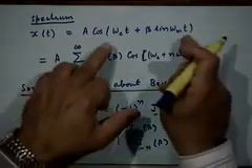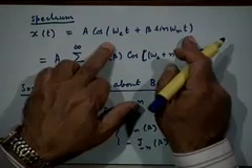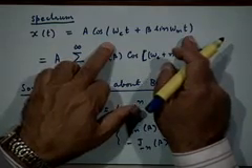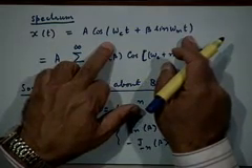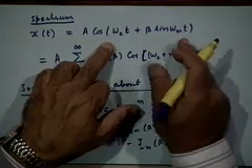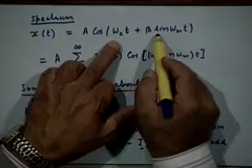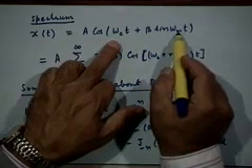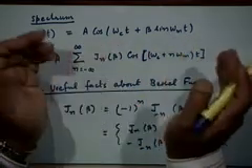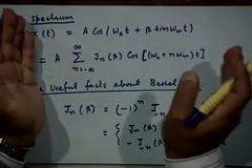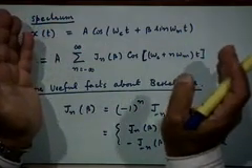If I differentiate the argument, what does the differentiated argument give me? The instantaneous frequency. So if I differentiate, what do I get? Omega c plus beta omega m cosine omega mt. Now can you give me a physical meaning?